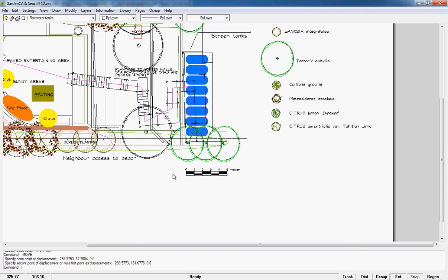The key issue is to accurately determine scale if you're going to put 1 to 100 or 1 to 200 down in that title block area. If you're not, you can always write not to scale, and you can use different sorts of scale factors as you're putting this in. You can even do it by eye.